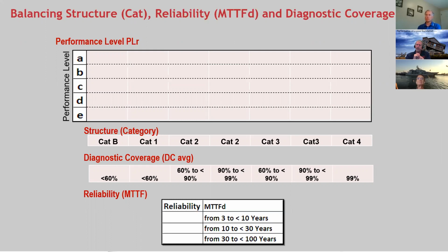SRP/CSs, safety-related parts of the control system, the standard also said you need to have, and in the example we used, we said we had a high risk, and that high risk equated to a category 3 PLd implementation in our safety circuit. So we are there right now. So we know that we need to get to PLd, category 3, right? So how do we get there?